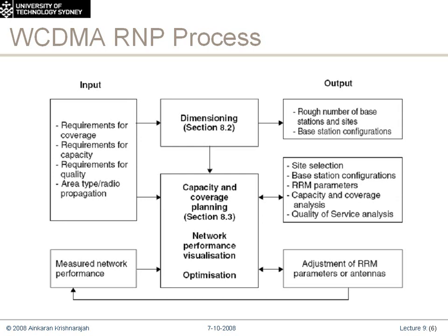When you have figured out the number of base stations needed to support a certain area, you need to figure out where to put them. Where is the most optimal location? Now, a planning tool ideally will uniformly spread them out in a very crude sense, but it has to take into account the buildings and the terrain. You can't put a base station in the middle of a lake, for example.